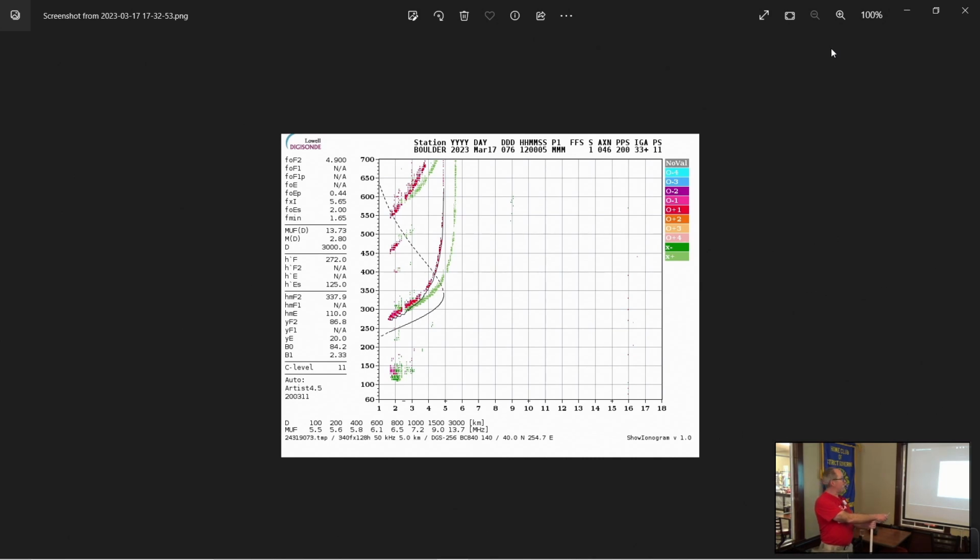And an ionosonde, a vertical ionosonde, which is what this is, does exactly what we want to do with NVIS. It has an antenna that shoots pulses of radar, HF radar, straight up. And it listens for echoes coming straight down. And it times that delay to figure out the height of the ionospheric layer. It starts at 1 megahertz and sweeps up through 18 megahertz. So it plots the height of the reflective layer versus frequency.